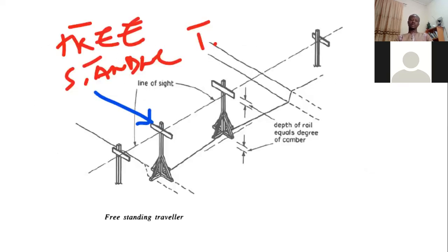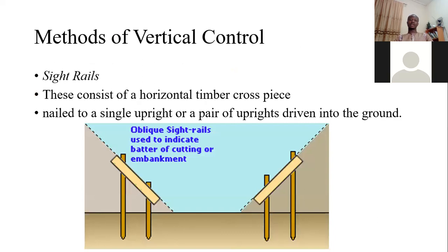That means, let's go back to this diagram. I think it came in the wrong place, but you can see that here there is an embankment, with oblique side rails, which are actually called butterboards. Sloping rails or butterboards are offset from the actual slope. In this diagram they seem to be flush with the actual slope, but that's not the way they're done. They're done in such a way that they are going parallel and offset from the actual surface.